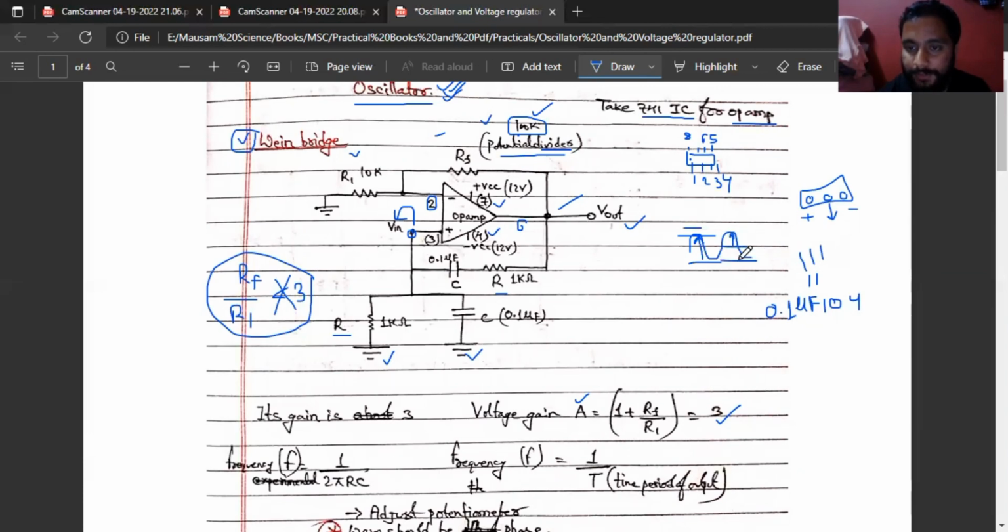We can take this total value from crest to trough. The total height from crest to trough is known as the voltage. We can see at what setting the oscilloscope is kept, and divide: 5 divisions is this much voltage, and some other number of divisions is that much voltage. In that way we can take it out.